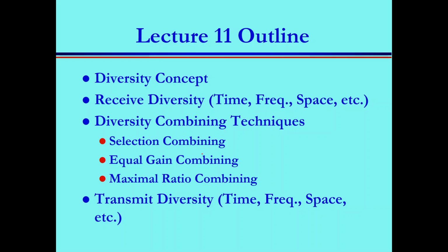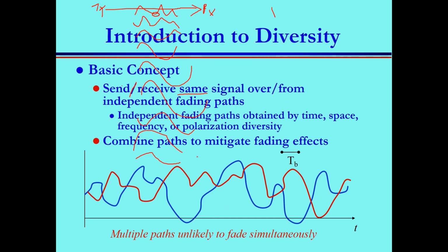For example, when you transmit your signal, and because of the movement in the channel, you receive it at different frequencies. So it's basically the same signal, but you are receiving it at different frequencies. F1 plus delta F1, F1 plus delta F2. This is also diversity. We call the first type of diversity multipath diversity. The second one, we call Doppler diversity.